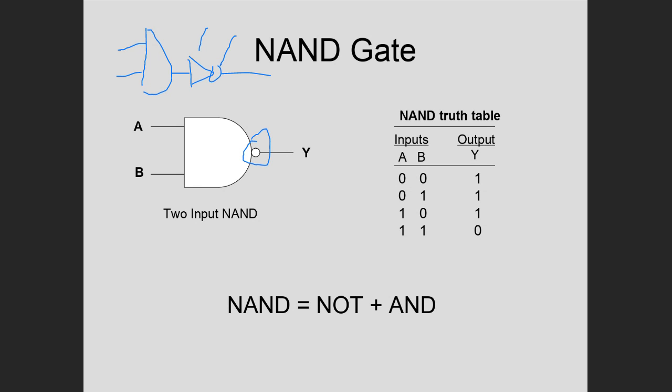So this is a combination of the AND and then the state indicator from the inverter for the NOT. And instead of drawing that whole triangle, we just draw a little bubble. That's why earlier I said I just think about when those zeros and ones are flowing from left to right through a chip. Anytime they hit a bubble, they're going to flip state. They're going to change states.